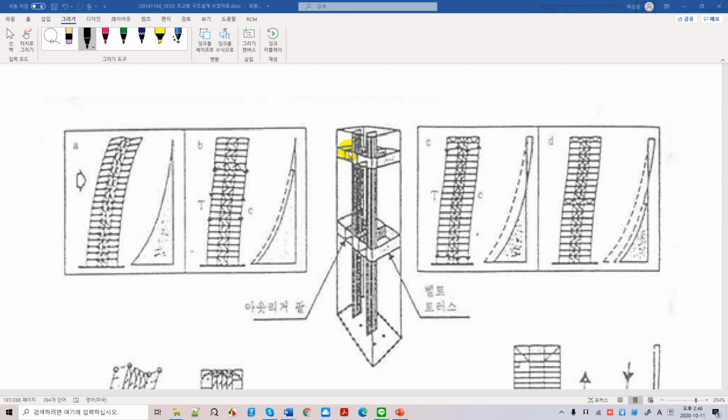Okay, and we have outriggers right here, and right here, and you see how the moment EI diagrams change, thus reducing your deflections, and this is very good. And also this is very simple to simulate using MIDAS. And I'm going to show one of the computer output illustrations after you put in outriggers at the end of the lecture today.